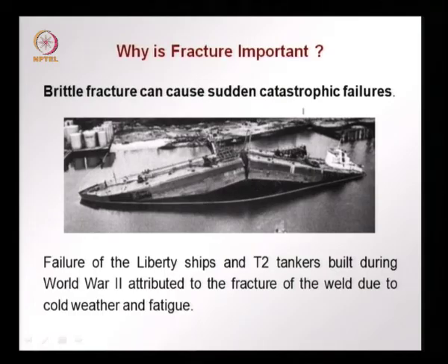Another case that we have already discussed is that of the failure of the Liberty ships and some T2 tankers that were built in World War II, and a similar behavior also happened in the Titanic, or what they say happened to the Titanic when it sunk. Here the weld that was used, due to the cold weather and fatigue, became brittle and a crack propagated. This is what was seen in one of these ships in the Boston harbor. A crack developed and suddenly this ship broke into two.